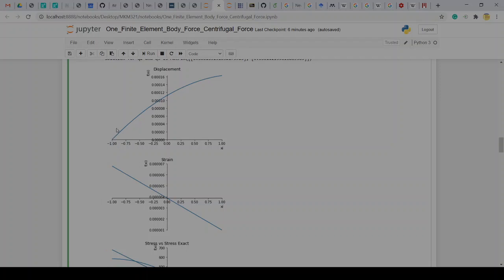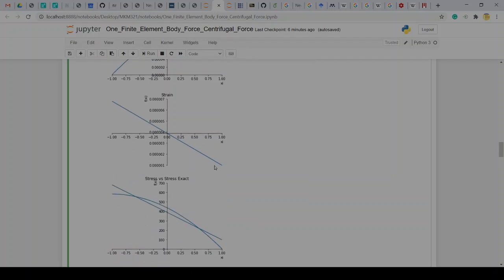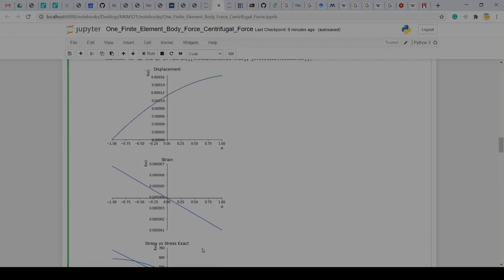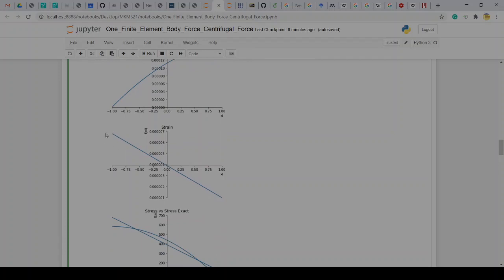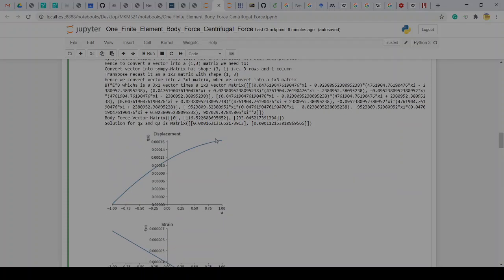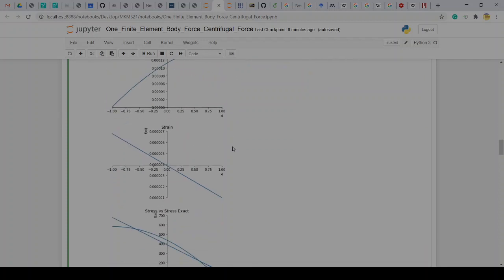So we see the displacement slope. If you want to relate that to strains, we can see that's the highest here, and it tapers off towards the right. So that is what we would expect to see. Again, this is a quadratic function for displacement, so the strain must be linear. So that is what we see. It's just the derivative of this quadratic field, which is a linear field that we see out here. And I see the strain is the highest at the place where it's rotating, and I see the strains going down. I might have expected to see at that edge, on the right-hand edge, actually 0 strain, so that maybe this should have tapered off completely flat there. So that is an expectation that one might have.